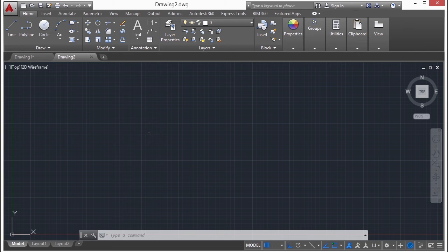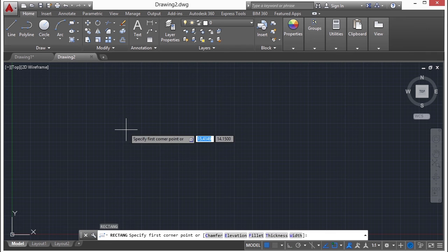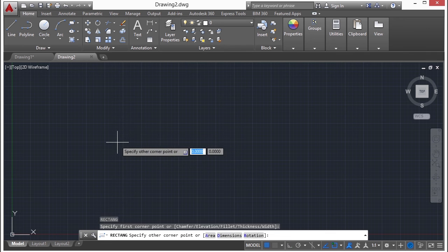Now we're going to start drawing a rectangle, and we're going to use the rectangle command. So just type in on your keyboard REC for rectangle. That's a little keyboard shortcut, and we'll talk about those again later on, of course. This will just be a way for you to use your commands in a shorter way. You can get to them much quicker. Press the Enter key.